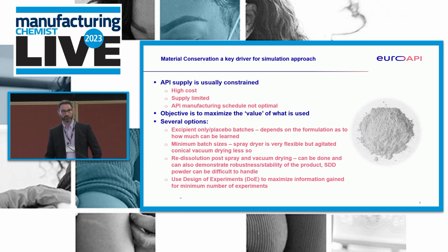We can look at redissolving after we've spray dried. We've done that a few times. It's not the nicest thing to do. After the spray drying, the powder can be quite difficult to handle in terms of redissolution. And there's always a question mark over potential degradation, the amount of reprocessing the spray dry dispersion will tolerate.